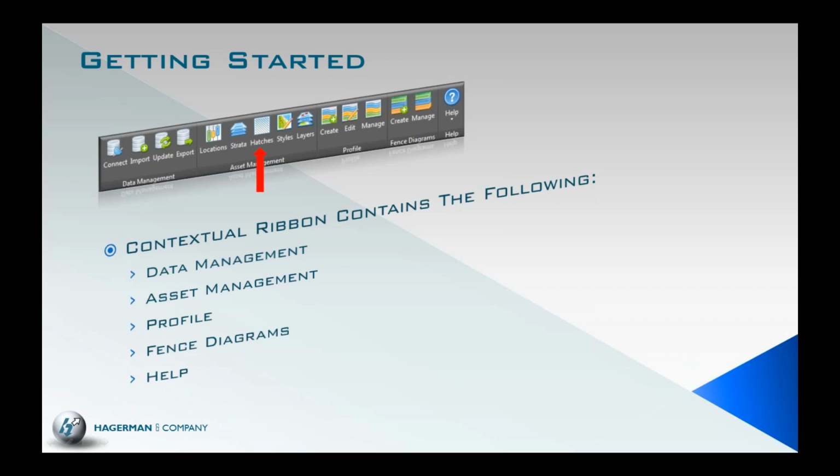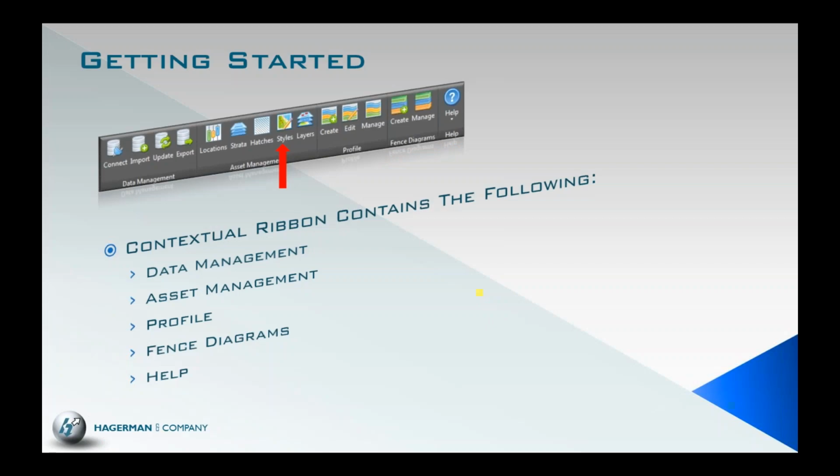Okay, so you can make up your own hatch patterns, color, scale, rotation. All right. You also have the ability to set styles. Okay. Now the styles are going to be somewhat similar to what we see under Civil 3D. I don't quite know what's going on there because you're getting a kind of a funky little flicker, but I apologize for that.